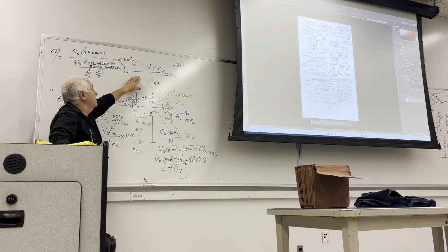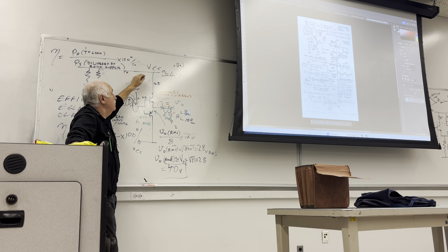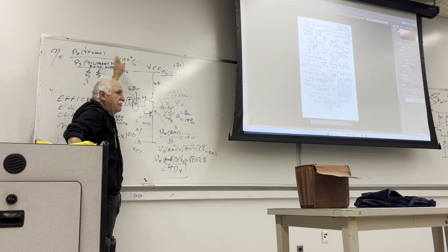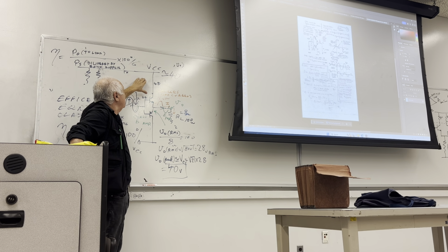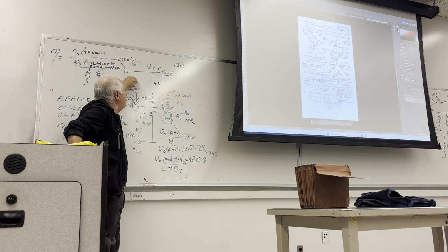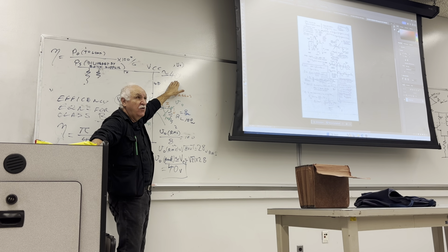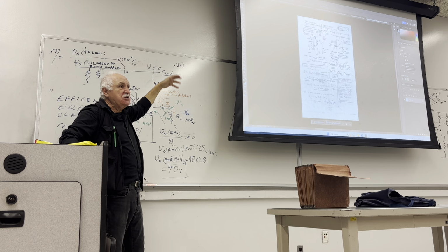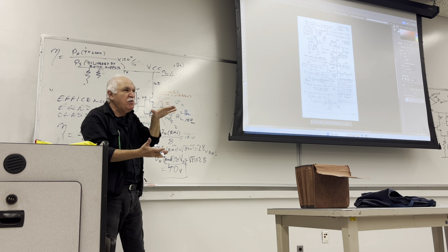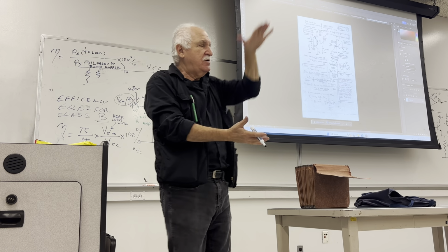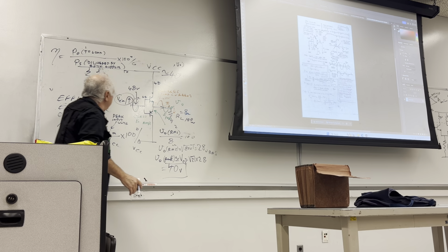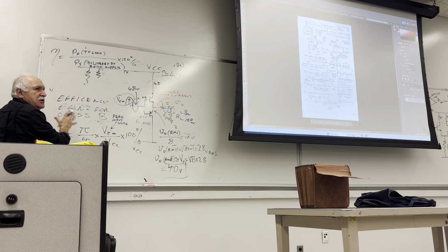Of course, 40 is not enough, because this base usually doesn't go and reach all the way, it will run out of bias. It should be within 90% of the 40. So I would say, if it comes to 40, your calculation, go 45, 46, you see, for the power supply. So there will be a little room for the maximums, because you've got biasing to do in here. It feeds the rest of the amplifiers in here.